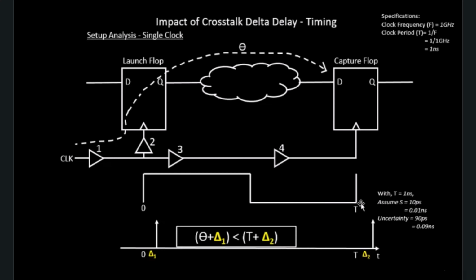So we have to capture that uncertainty. It's not certain that the clock edge will arrive exactly at t, so we have to account for that uncertainty as well. We are taking that as 90 picoseconds over here. This is only the uncertainty, and there are other ways of modeling this, like on-chip variations and so on. We'll look into that in the STA lectures, not here.